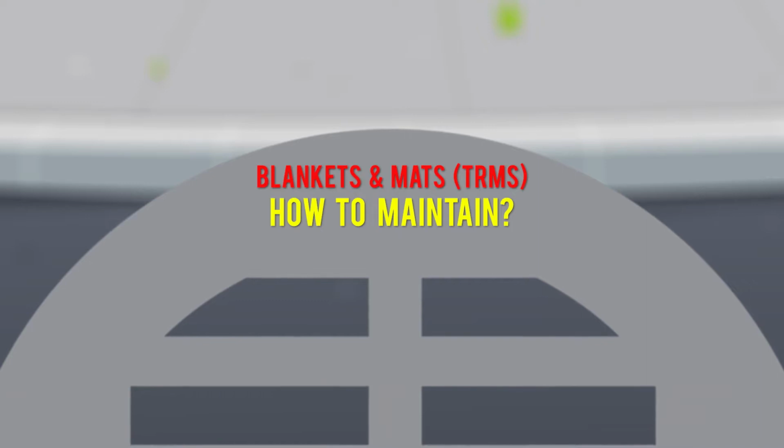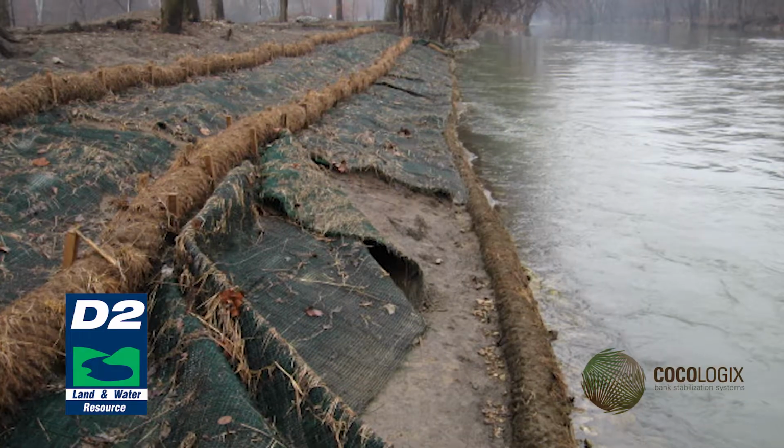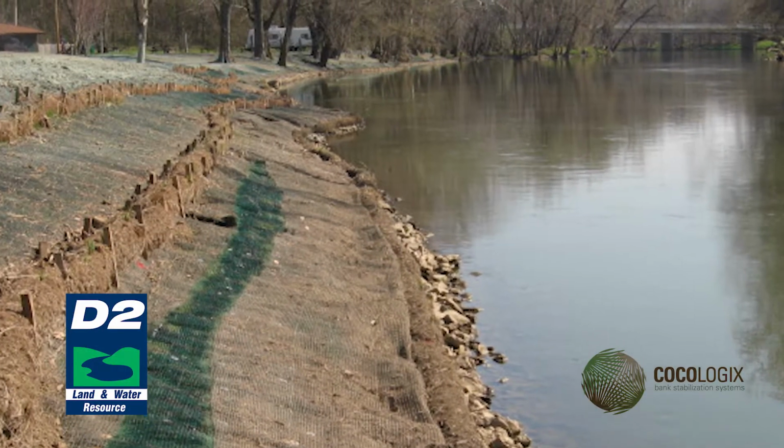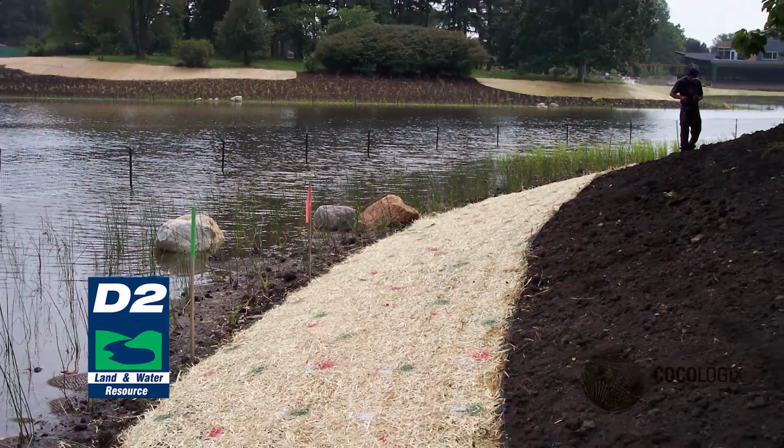How to maintain. Pull back the portion of the blanket covering eroded areas, add soil and tamp, reseed the area, replace and staple the blanket. How to inspect. Inspectors should check for erosion or displacement of the blanket.